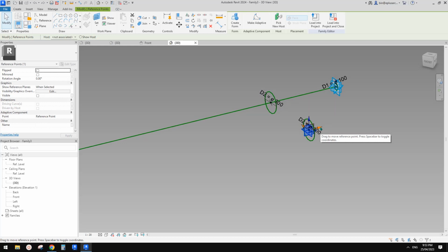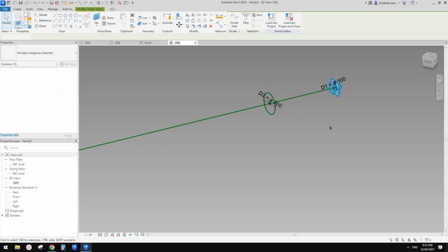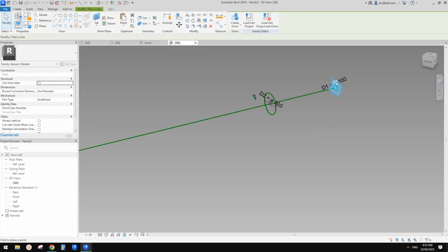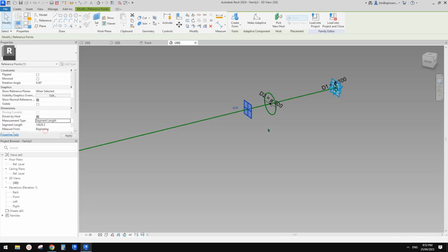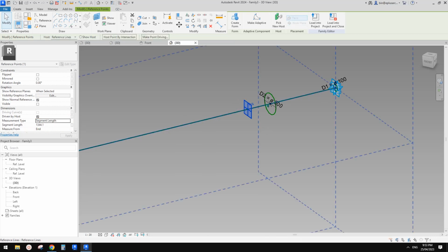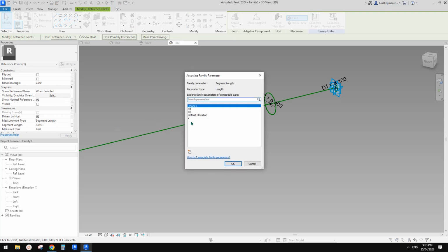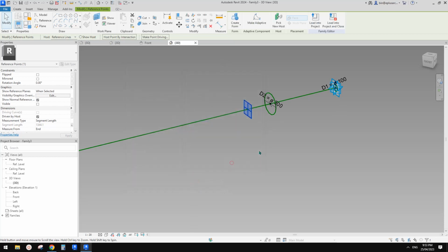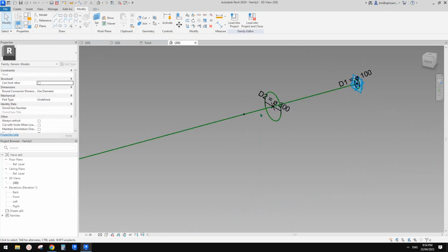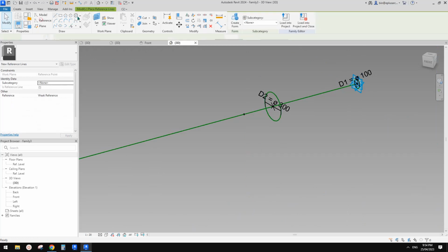How can we fix this one? Maybe do this. I'll just create another point, manually place it here, and then change this one to segment length. Flip. And I'm going to create a new parameter. So instead of x, I'll just call it x2 instance. Okay, so I want this x2 only 1 mil next to this one. But before that, let's create a profile onto it first.